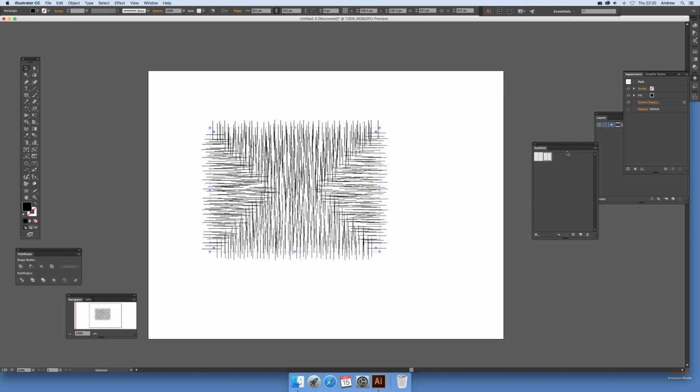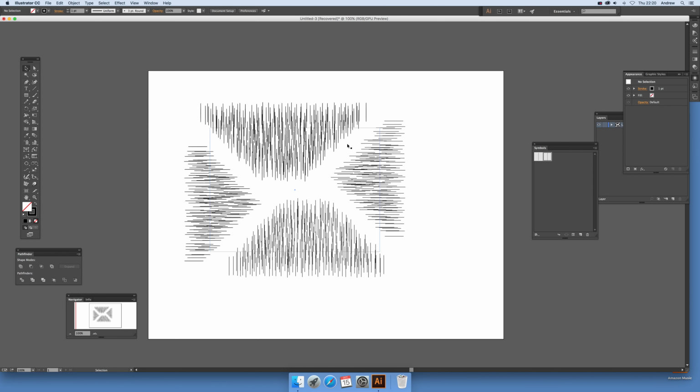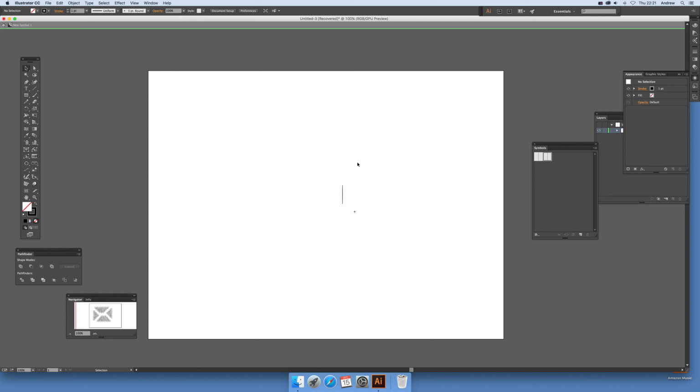Now what you can do, of course, just quickly go there and click. And now there's the registration point just there. So you can move that just slightly and come out of that. And straight away you can see what happens. It's still following the path, but it just separates, pushes out. So you can modify the design quite dramatically just by changing that.